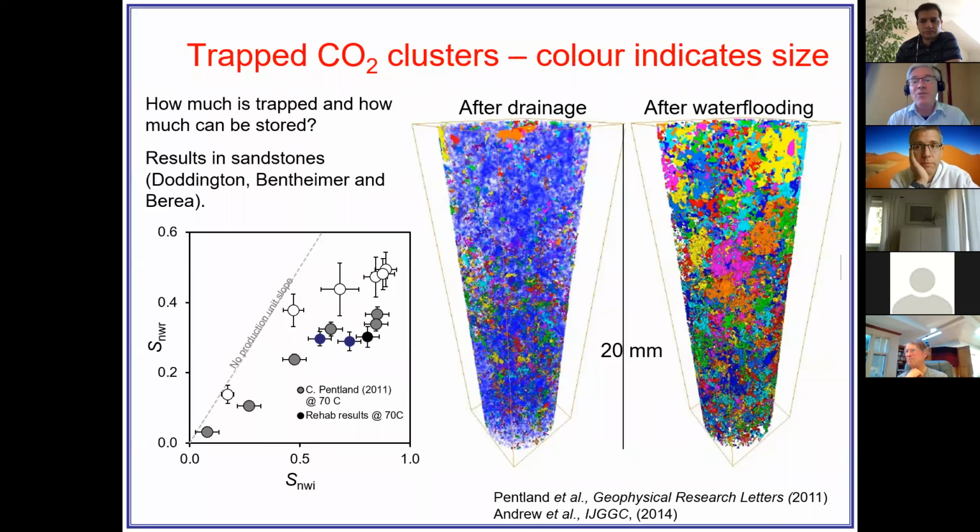that porous media flow is so complex that the idea of really being truly deterministic is, I think, not going to happen. So I think what you should view is, as long as you get the same statistical properties, which are how much is trapped, flow properties, etc., I think you're doing okay. So that's what we're doing with our network modeling. We know we're never going to get a model that is perfect, that gets every single pore right, but we can certainly drive down the error to well below what you'd see in repeat experiments. But you're never going to get it to zero.